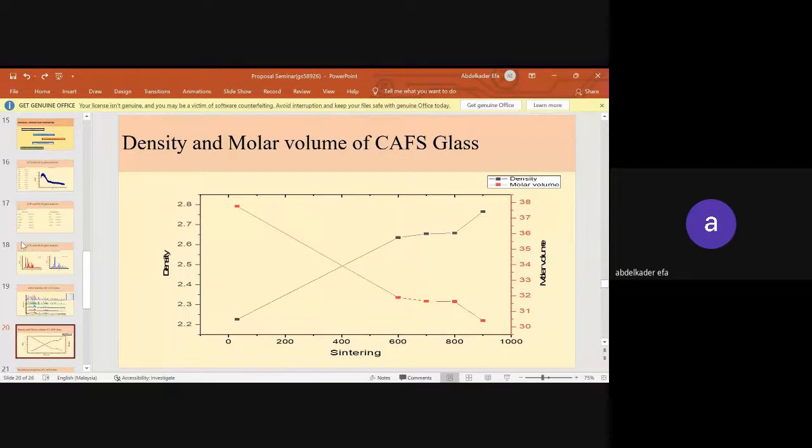The glass pellet becomes significant at 900 degrees. This situation happened because the particles underwent sintering, as well as the development of grain growth in the sample. Then the particle packing in the unit volume increased, and it can enhance the particle contact for crystallization.